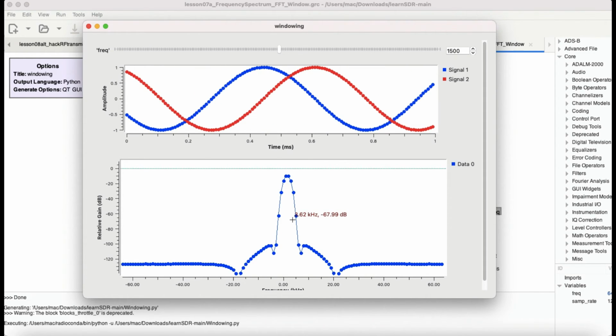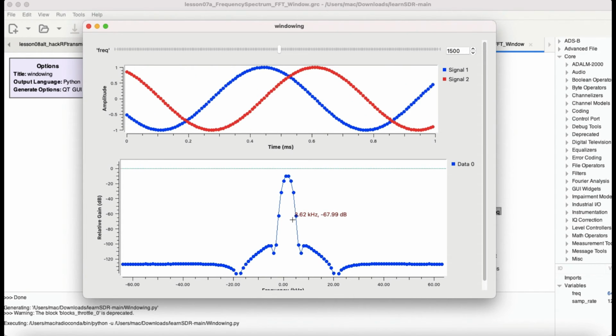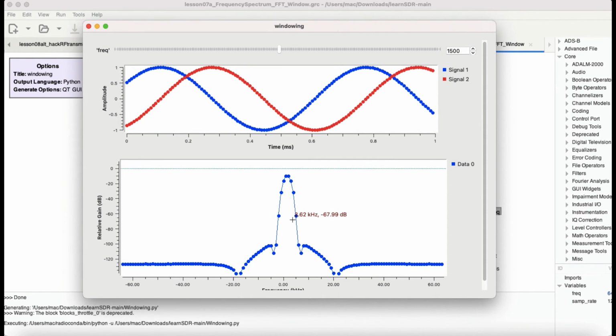It is quite easy to understand with a rectangular window, because a rectangular window, if you were to look at it, is basically just a low pass filter. So you're multiplying its transfer function with the signal, and you're getting your signal out. If you have a very broad frequency range, a broadband signal, then no window, or rather a rectangular window, is good enough.